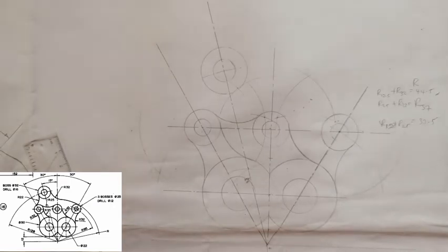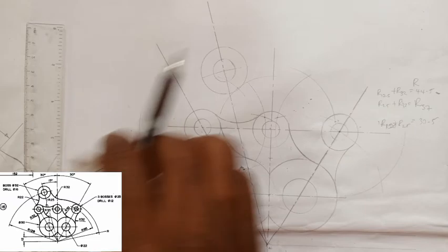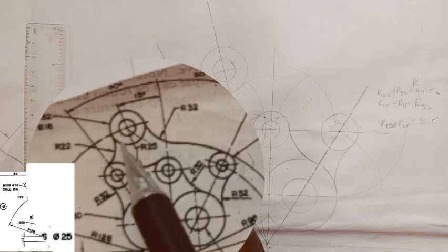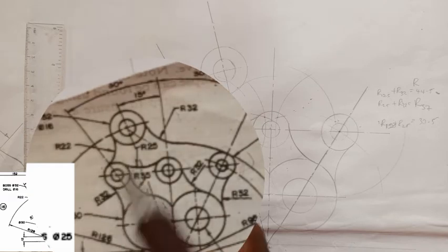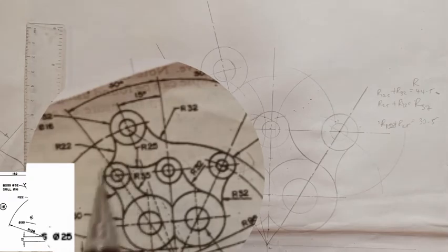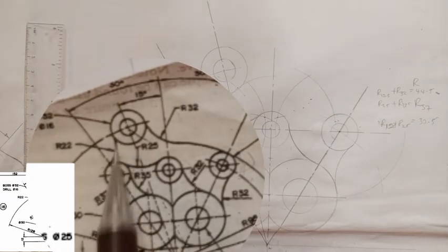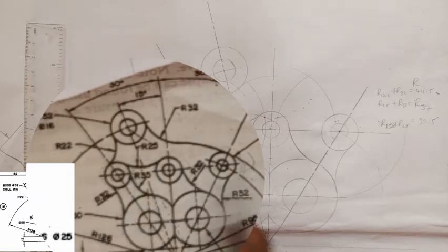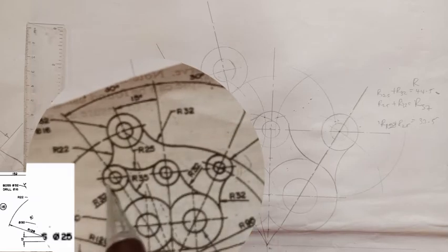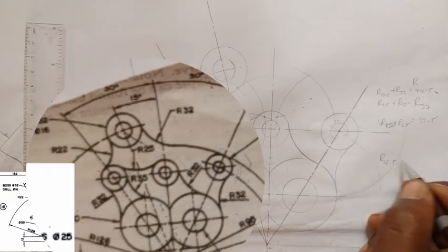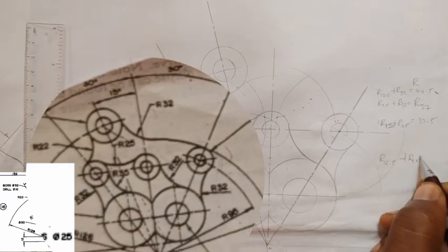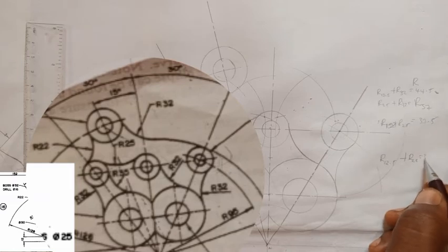Alright. So we've done this aspect now. What's remaining here is this arc, that is 22, right? Since this is 12.5 and this is also a porthole, a hole we have to fill, you're adding the radiuses. From the diameter of 25, this is 12.5. So I'll say radius 12.5 plus the radius 22, and that will give us radius 34.5. So 34.5 is the radius I'm going to use.